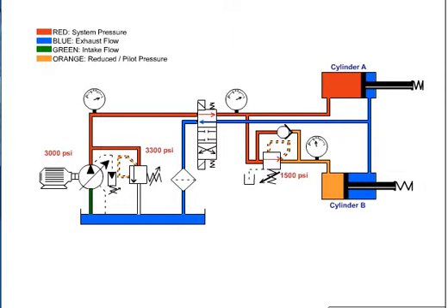At this point, the valve begins to close off, limiting any further buildup of pressure. As fluid bleeds to the tank through the valve drain passage, pressure will begin to decay off and the valve will again open. The result is a reduced modulated pressure equal to the setting of the valve.